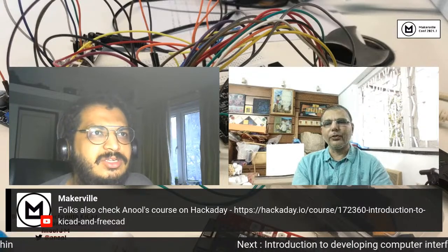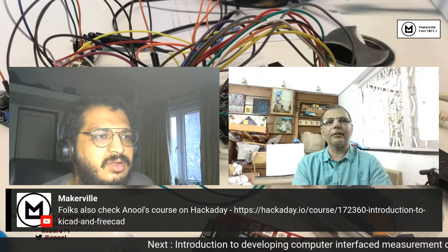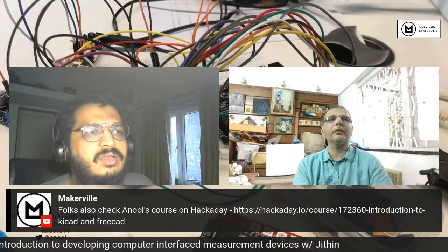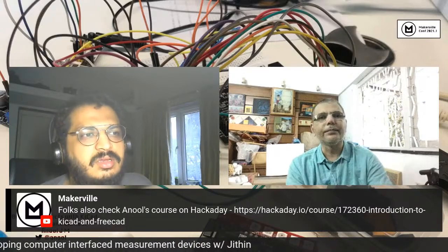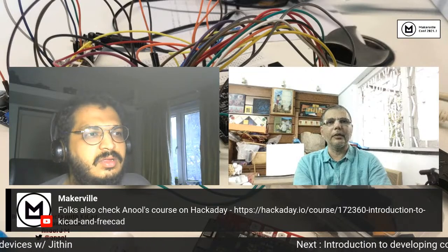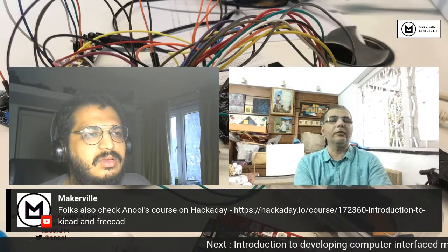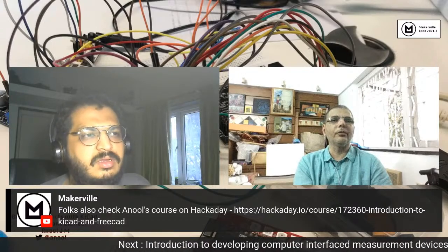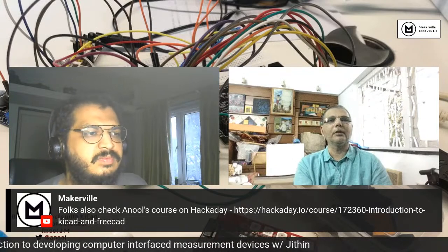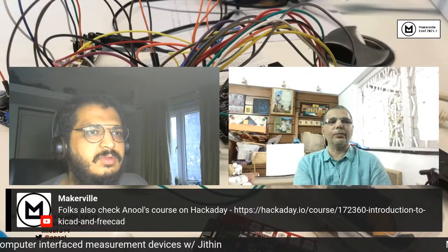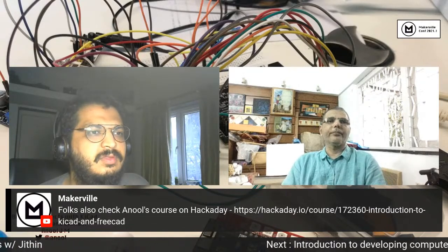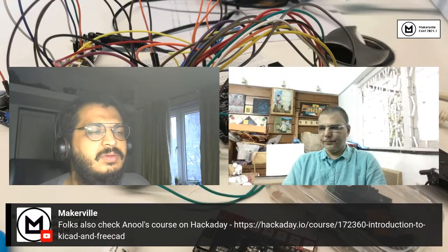But you know what? You can still get really nice results by just doing the KiCad plus FreeCAD route without involving Blender. You can get pretty close. Right. And there is a ray tracing workbench in FreeCAD. Sorry. And some work is being done on it. It's not perfect yet, and I have not been able to figure out how it works yet. But if that works, then you probably don't need Blender at all. You can do everything within KiCad plus FreeCAD, which will be ideal. Cool.